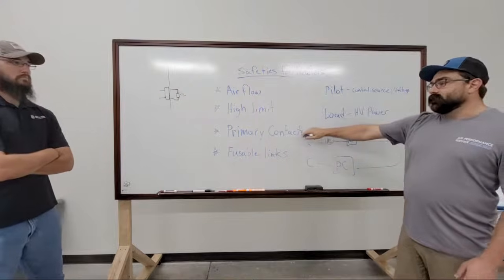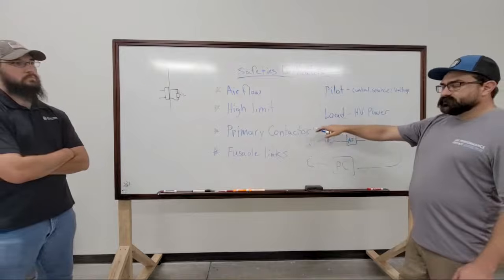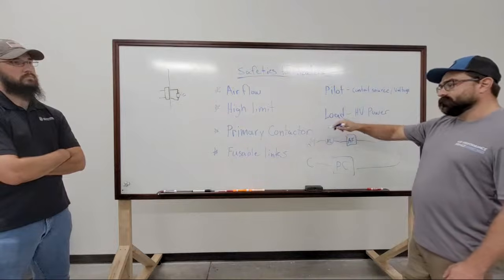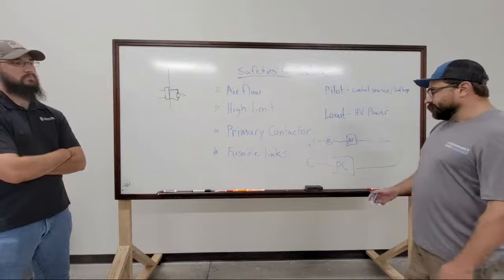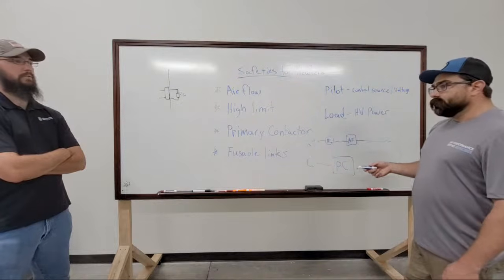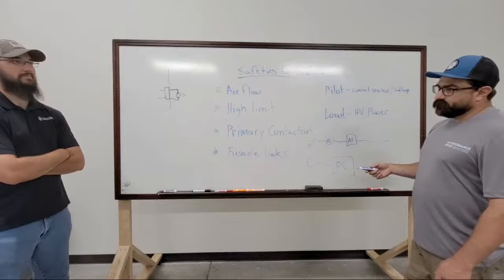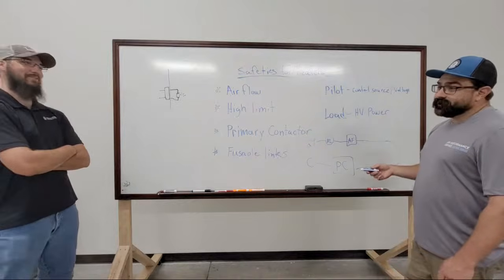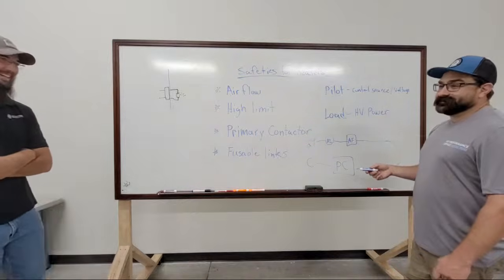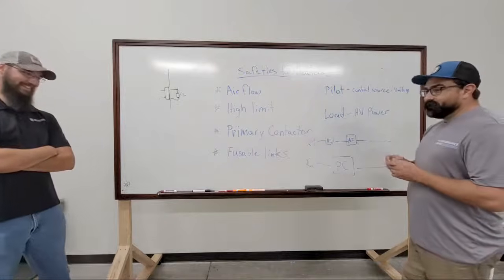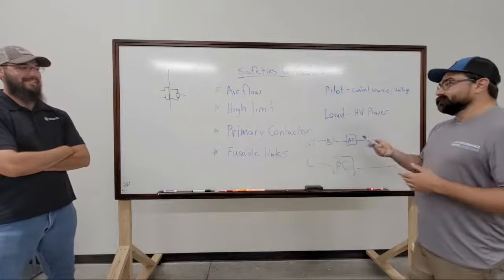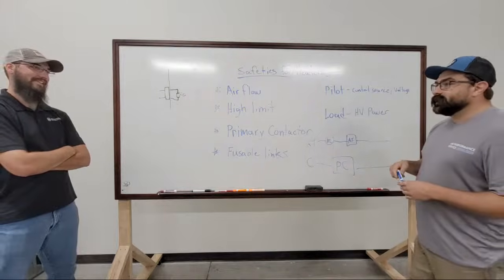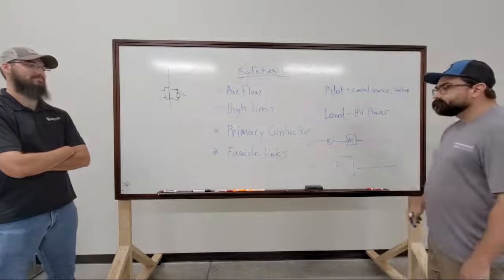Some of these can be mercury contactors in older systems. And then some of them will just be a definite purpose relay contactor. I couldn't tell you the last time I ran into a mercury. I can name about 7 buildings right off the top of my head. One of them is a project we're on right now, and it's a pain in the butt. And the one I did that SCR heater on the other day had a mercury contactor.